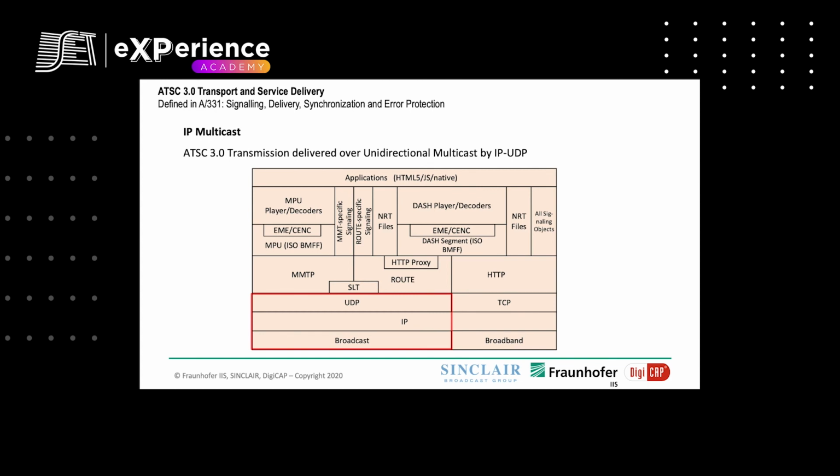Now, what does it mean that ATSC 3.0 is all IP multicast? From the perspective of the receiver, or what we commonly call the physical layer interface, it means that the decoded ATSC 3.0 emission is comprised of the individual IP multicast flows that represent a service. Whether it's MMT, ROUTE with linear AV, or data, each individual service is provided on its own IP UDP flow. This is very different than common MPEG-TS mechanisms, which deliver one large multicast mux, which becomes very problematic to decode individual services from.